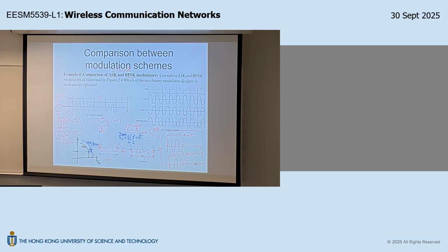And D2 obviously will be much smaller than square root 2. You can calculate this. It's a geometric problem. So therefore, you can see it and quantify how much worse, right? But in any case, even if you do not calculate this, you can for sure observe that D2 is much less than D1. So that means when you squeeze an additional 4 points onto the QPSK constellation, you get 8 points, so you increase the bit rate this way. But at the same time, your error probability will be higher. Is that okay? So that's the penalty.